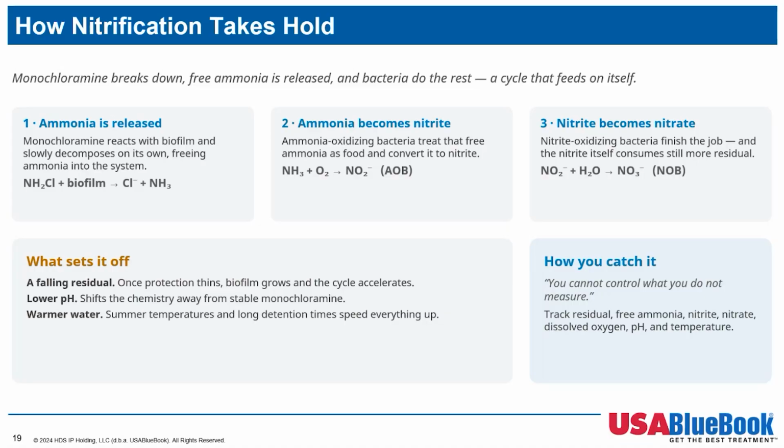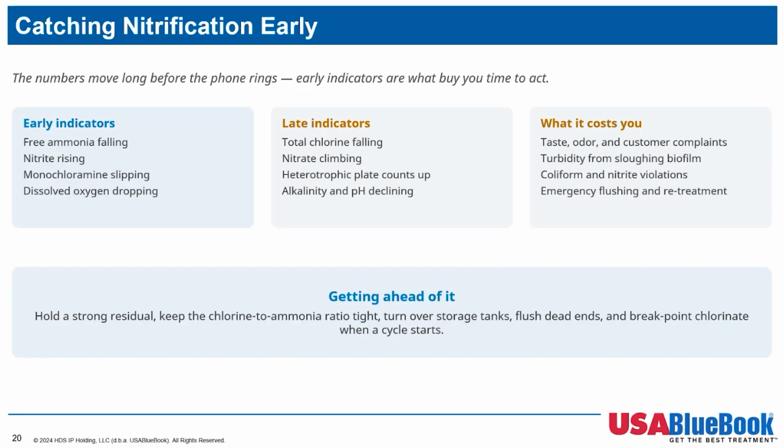Now, on the next slide, the good news is that the numbers move early. Right, so here's the encouraging part. The numbers change long before the phone rings. Free ammonia falling, nitrite ticking up, monochloramine slipping, even dissolved oxygen dropping. That's your window. That's when it's still a dosing adjustment.